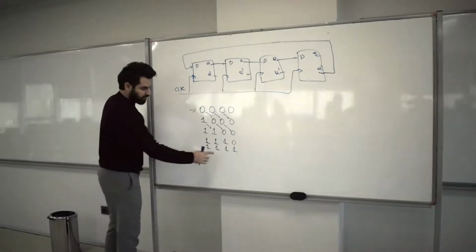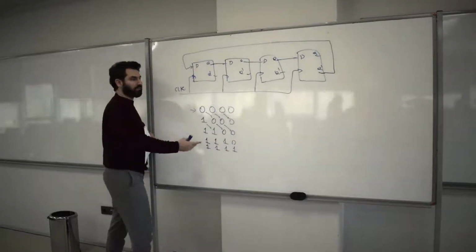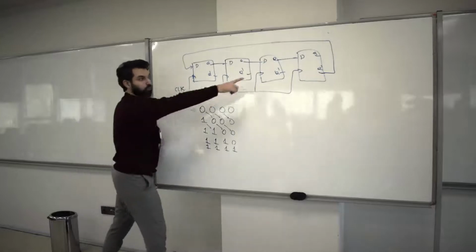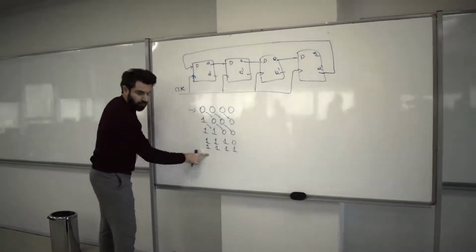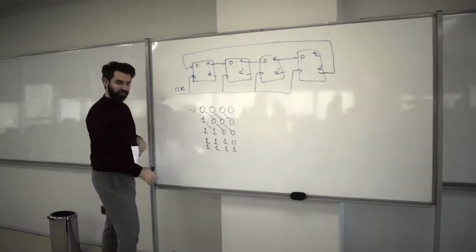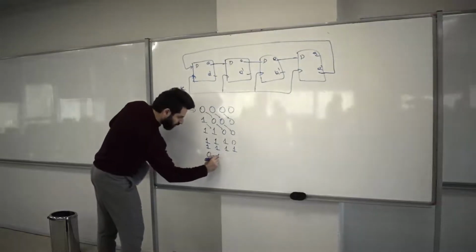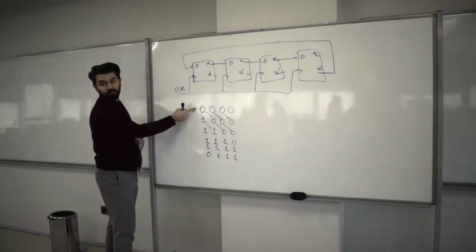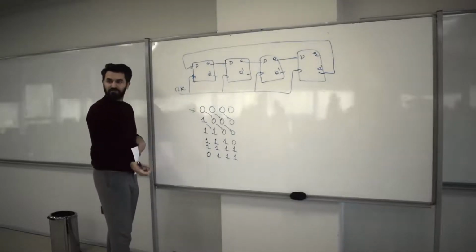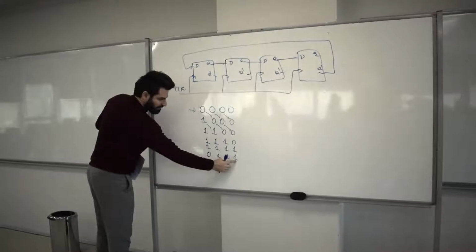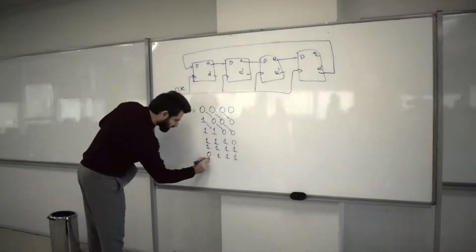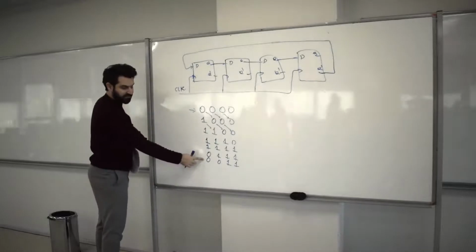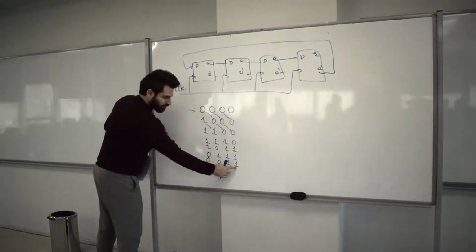Let me move on. So this now becomes 1. So when you have a 1 at the last flip-flop, the output Q prime would be 0 now. So now 0 is going to be pushed into the shift register. So you got 0, 1, 1, and 1. Still, this is something that I haven't seen before. Okay, so I still keep ticking. So now this 1 becomes 0. So I got 0, 0, 1, 1. Not there yet. So I continue.